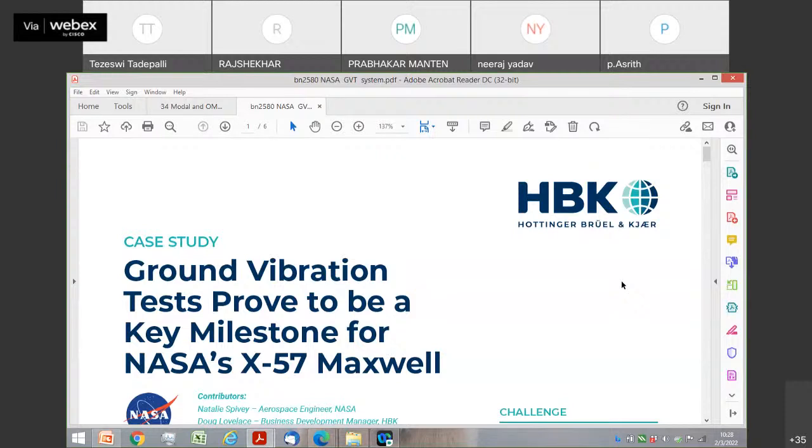Your dynamic range, for example, when I say 160 dB dynamic range, I'm talking of the comparison between a human hair and Mount Everest. That is the sort of measurement that I can do absolutely simultaneously without any ranging on your DAS. That's one. The second is you could use shock accelerometers which could easily measure 100,000, almost a million G.